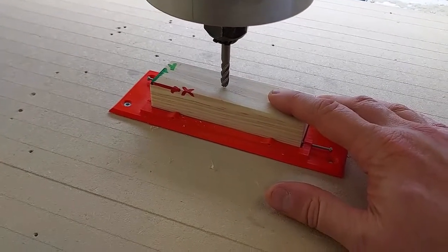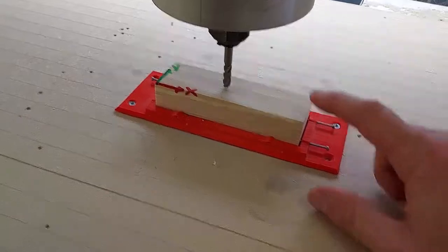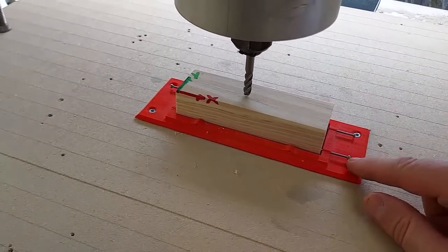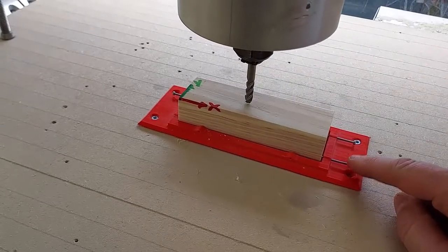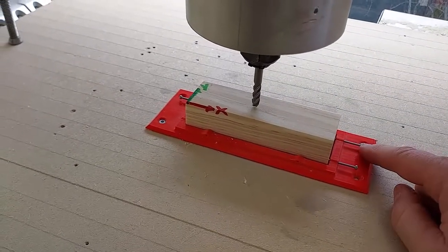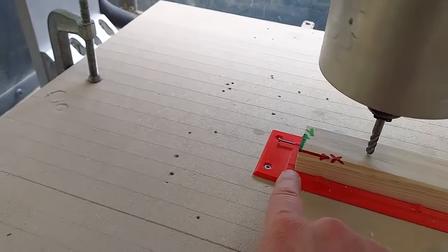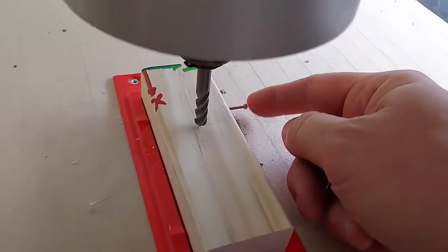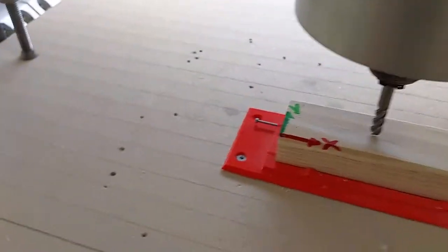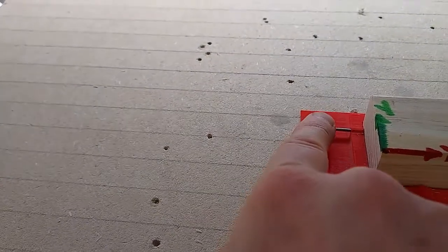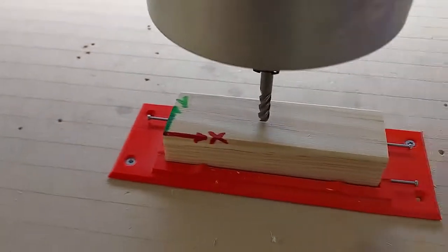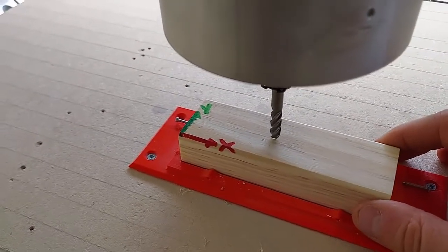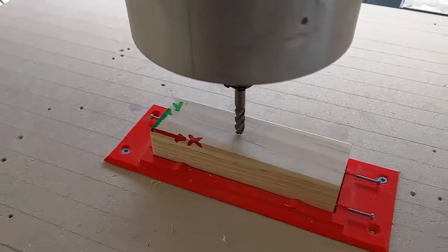And if you are my students, what you want to do now is press this on, turn the vacuum on down below, and then tighten these screws first, so it's backed up against this corner, and then tighten this screw next, and then lastly tighten this screw. Then give a little tug on your workpiece and just make sure it's in there and secured and it's not coming out.